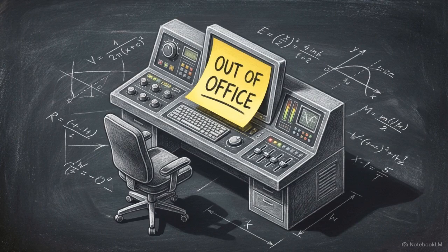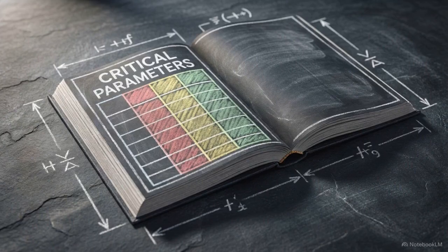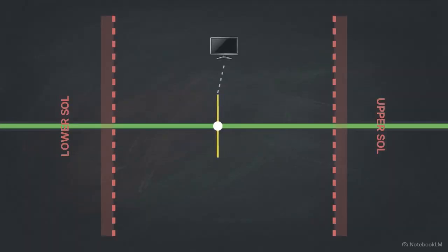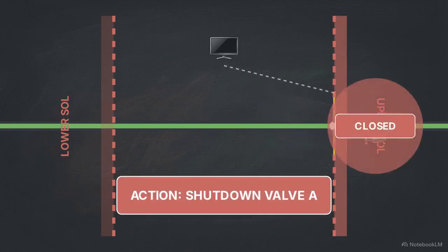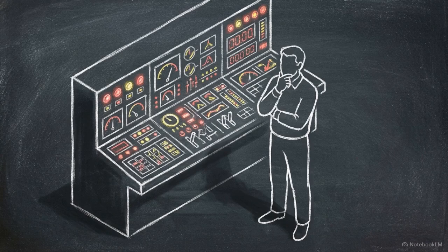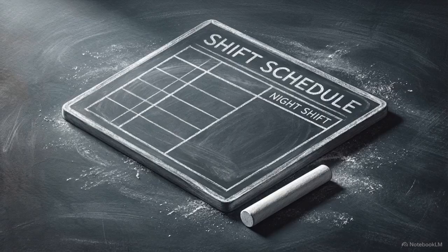for their judgment. Safe operating limits are the singular technical concept that provides this anchor, preventing catastrophic failure when individual experience is unavailable. These limits define the exact physical boundaries of a process and dictate the specific, predetermined actions required when those boundaries are approached. A facility operating without these documented boundaries relies on the memory of its personnel, leaving the safety of the unit to the variable experience of whoever happens to be on shift.